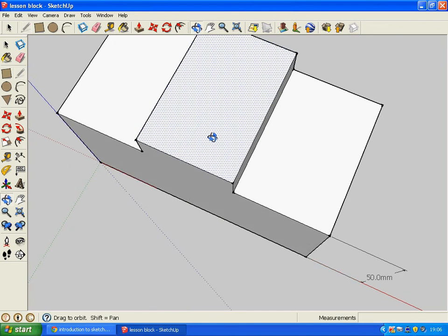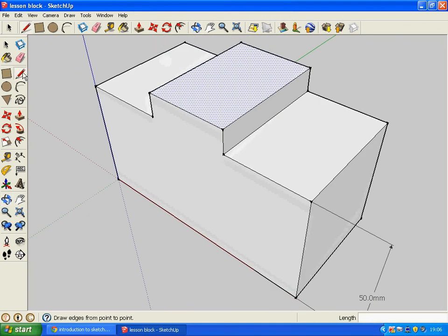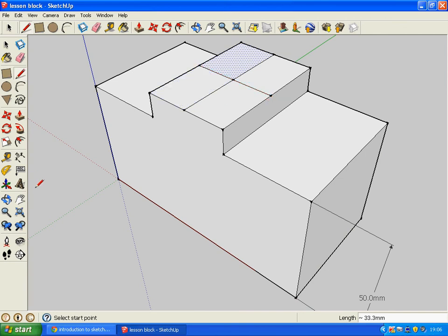Okay, in fact what I'll do is I'll just rotate this drawing around so I can see it a little better. Come to the midpoint, click, come along in the green plane, and then I'm looking for the edge on the further side. Similarly, I can come along this line to the midpoint, and then I can come across to the center. Now I can use my circle tool, and it will obviously intuitively go towards that center there, and I want a radius of 10. Press enter.